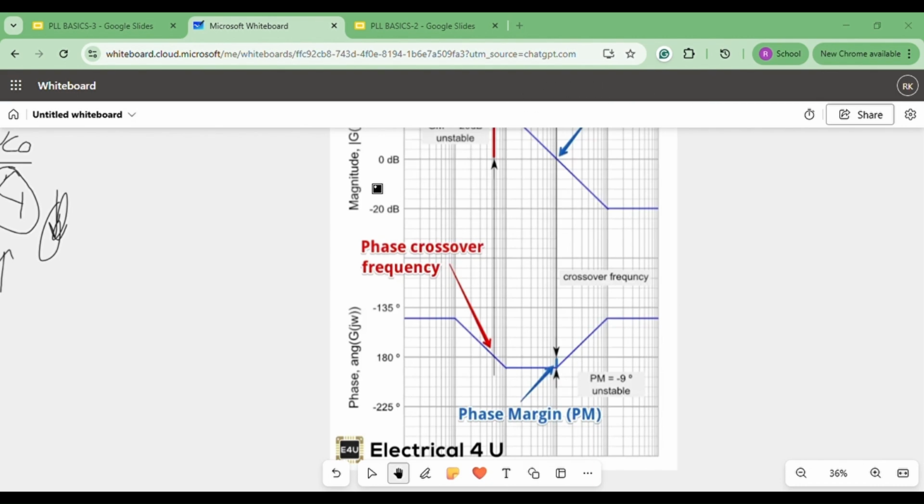Yeah, we'll go to our terminal again. So when we calculate, we have added this from the calculator to here. So we are getting a phase margin of 67.75, which is desired, and the phase margin frequency is 1.206. So how did we get it? This also you need to explore.